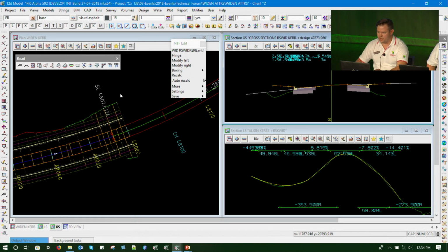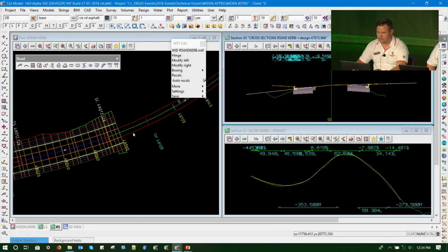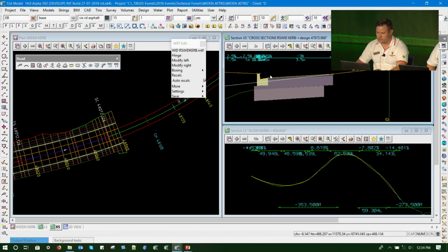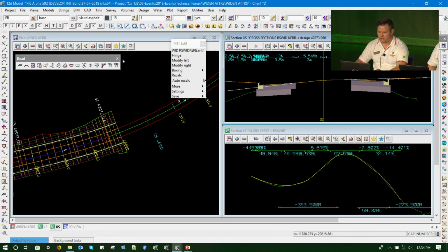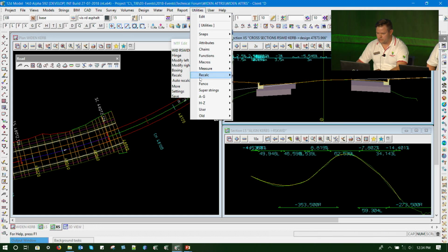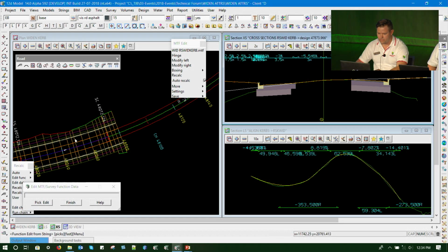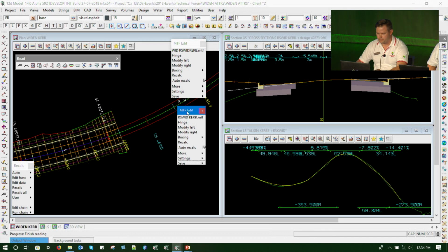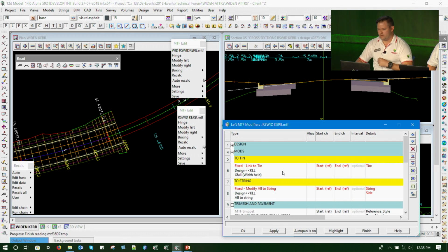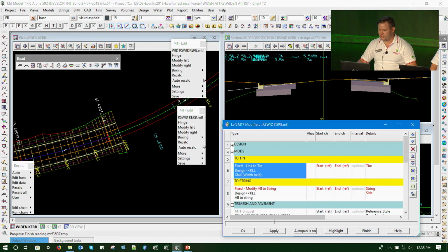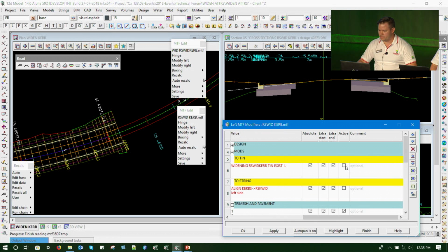All right, I'm going to open up the MTF editor for this road now, because what we want to do is make our curb lips come down onto this tin. So my recalc panel's disappeared. So I've already got the modifiers in there for this one. I've just deactivated it. So this is just a link to tin modifier. So I'm just going to scroll across here, activate it.